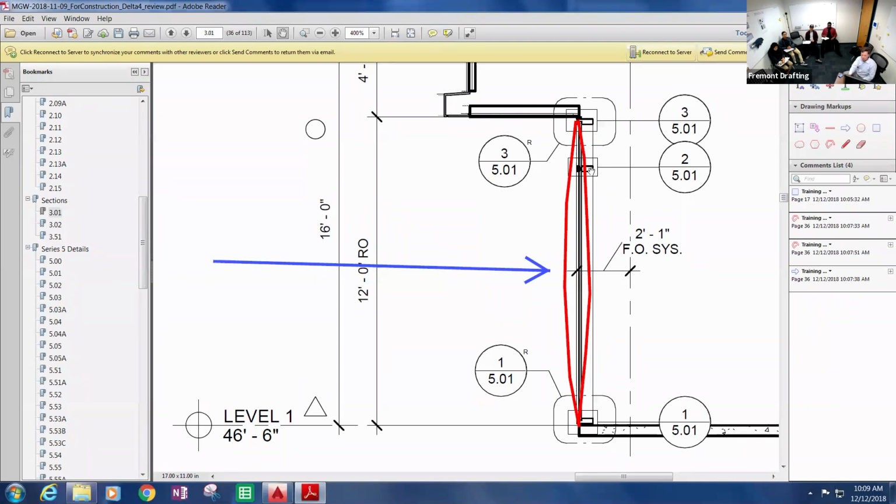Yeah. So if this horizontal was down here in the middle, and the mullion deflected 3/4 of an inch, none of the lights of glass are actually deflecting 3/4. The head has moved over 3/4, and now the deflection is within that. So typically when you have multiple lights of glass in a span, the 3/4 of an inch, while the specs still ask for it, and so a lot of times we still try to hold to it, we're never going to have that issue with the glass. It's really when I've got an opening where it's a really tall light of glass.